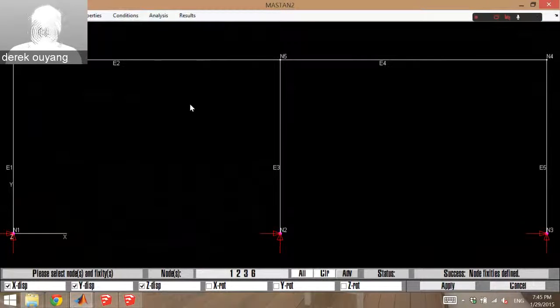So that might be the same for the structure, because the lateral system isn't directly feeling the wind; it's getting it at each floor, right? Because it's not like the column next to it is feeling the pressure of the wind.